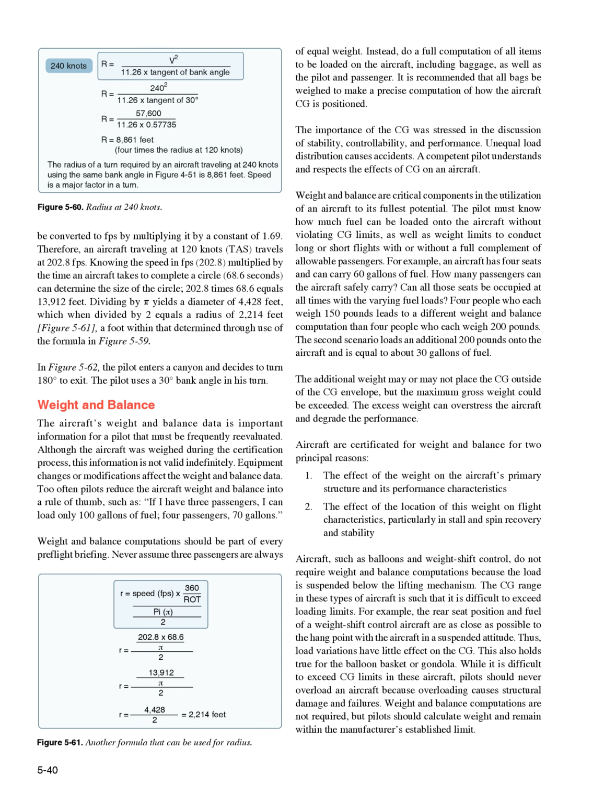While it is difficult to exceed CG limits in these aircraft, pilots should never overload an aircraft because overloading causes structural damage and failures. Weight and balance computations are not required, but pilots should calculate weight and remain within the manufacturer's established limit.